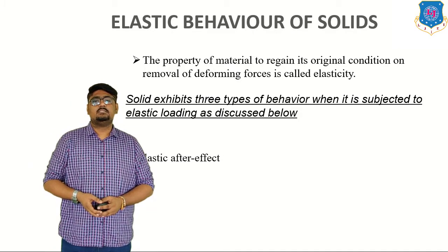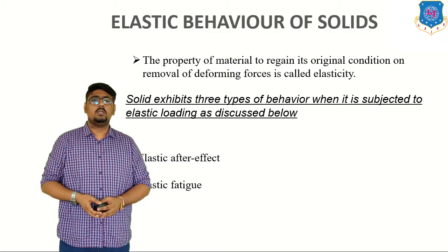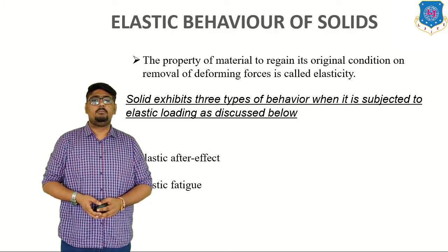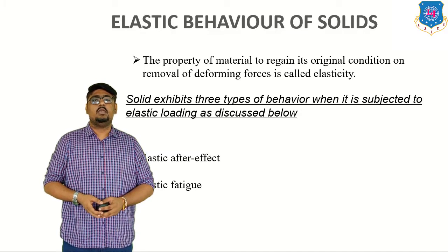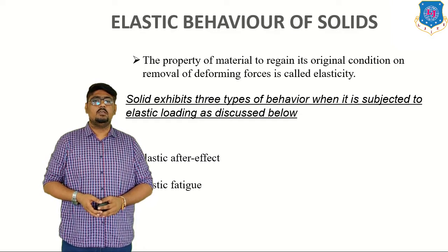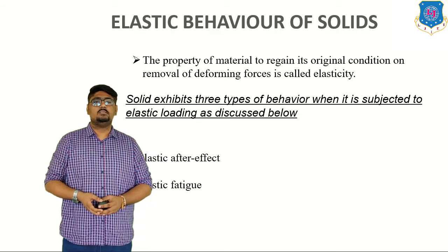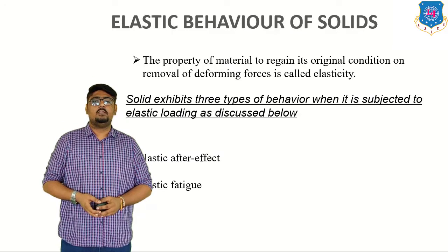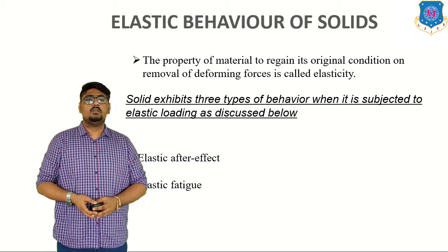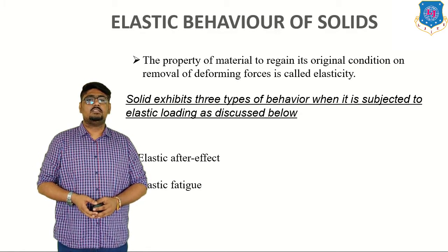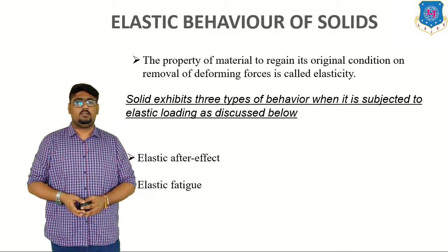Next is elastic fatigue. As we know that when an elastic body is loaded within the elastic limit and kept strained for a short time, extension is produced in it, and on removal of load, it is expected to regain its size. If such an elastic body is subjected to this type of loading and unloading conditions, then it becomes less elastic. Due to the continuous alternate strain, the elastic body becomes fatigued. This phenomenon is known as elastic fatigue.